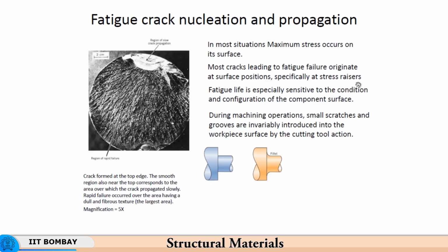Now this is because when there is plastic deformation and the material is being subjected to repeated cycles of plastic deformation, the residual ductility of the material gets exhausted over a period of time. Wherever the stress gets concentrated, you have a significant amount of plastic deformation taking place with every cycle. This accumulated deformation exhausts the ductility, and at some point you have an origin or initiation of the crack.